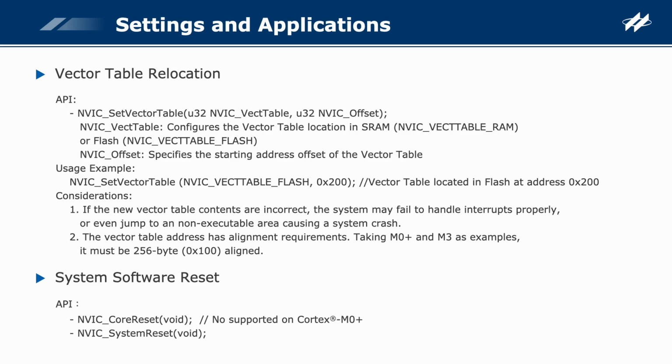NVIC software reset function, as shown in the following APIs. NVIC_CoreReset resets only the MCU core, while the state of the peripheral circuits is maintained. Additionally, Cortex-M0 Plus does not support this function. NVIC_SystemReset resets the entire MCU, including the core and all peripheral circuits.